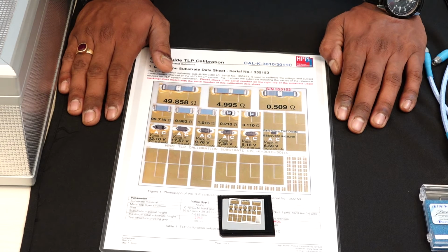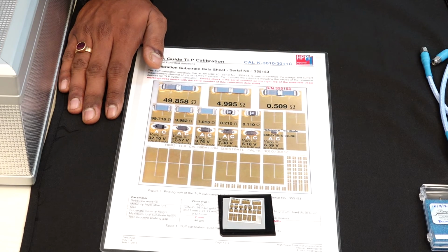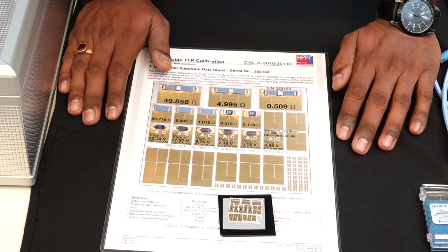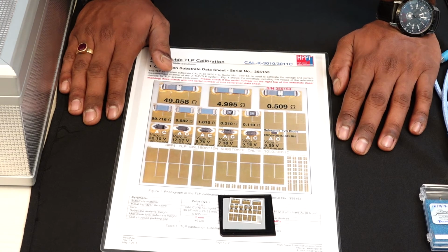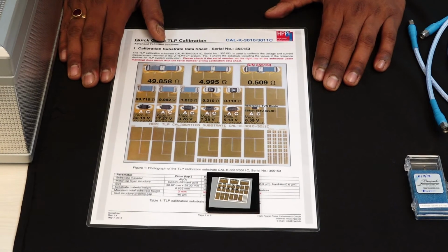The calibration of the voltage channel line is done through a Zener diode, and the calibration of the other line is done through a diode and a resistor. They are also calibrated using a set of open pads, where the calibration of the voltage channel is done through an open pad and a Zener diode. When you have these open pads, you would not expect any current to come through the device, right?